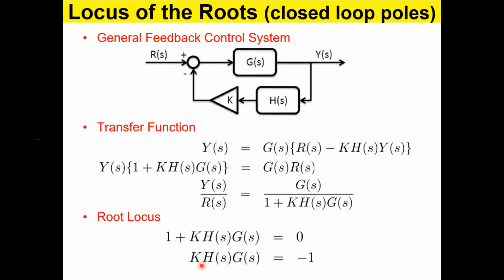I think you saw one of these root loci in the previous lecture, previous in the sense today, just before this one, where you saw k equals 0, k equals Kc, k equals Ku, and the poles move towards each other or away from each other, and then they meet up in the middle, and then one goes north, the other one goes south. So that is what is called the root locus, basically. As you change k, the poles move. So in fact, we have done one root locus already, but you did it in a cut and dry manner, not a methodical, mathematical manner. So now we are going to figure out what are the rules here, how we can draw a root locus, right, systematically.